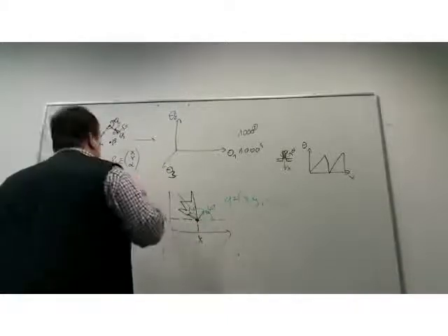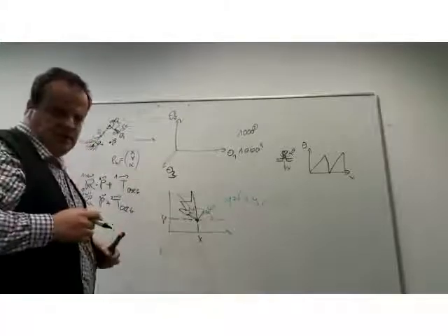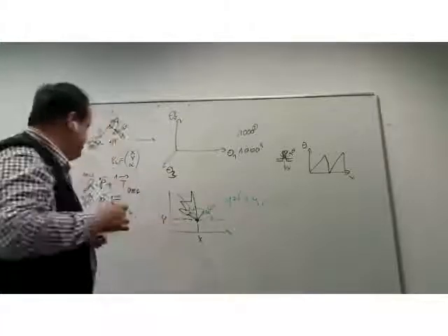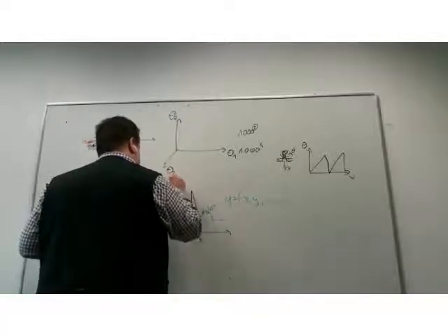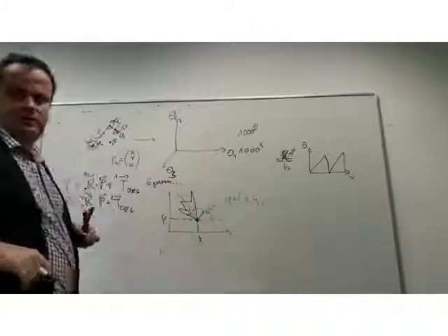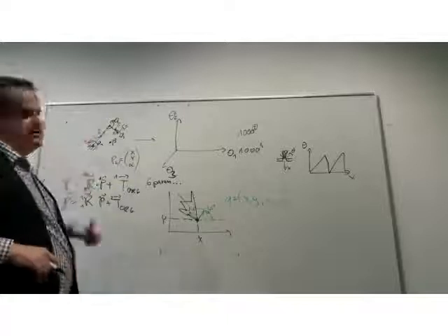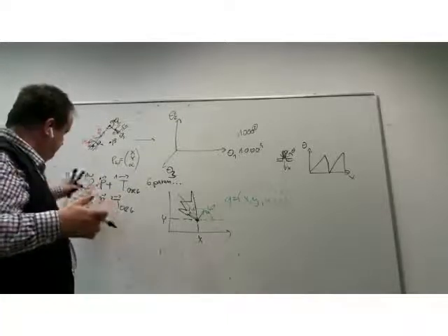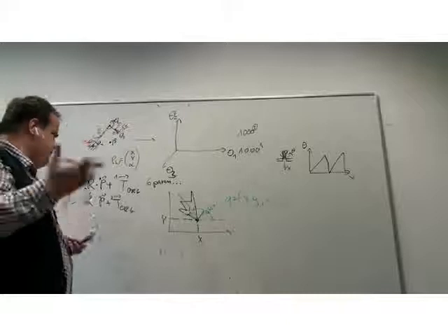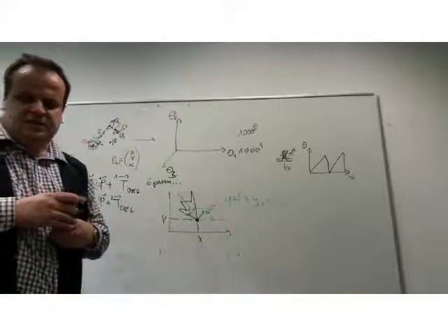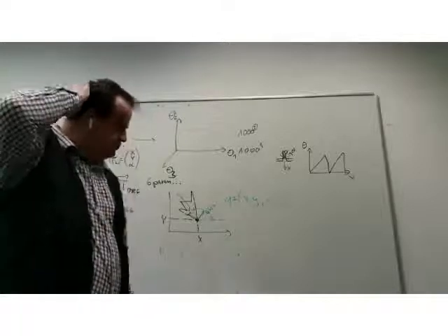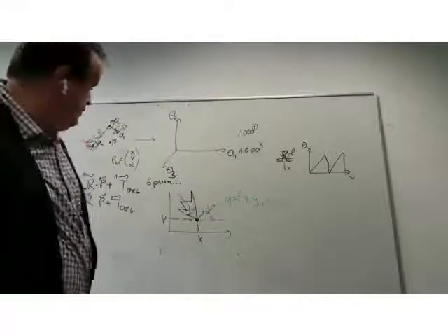So if we don't constrain the choice of parameters, it will be 6 parameters which we will need to define for each axis. 3 of them will define how the orientation changes, 3 of them how the position changes. And we will see that this may not be the best way of dealing with this.